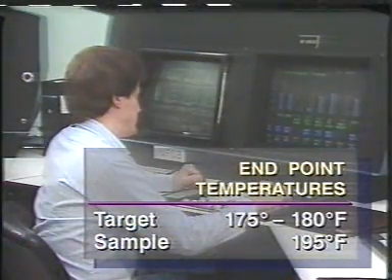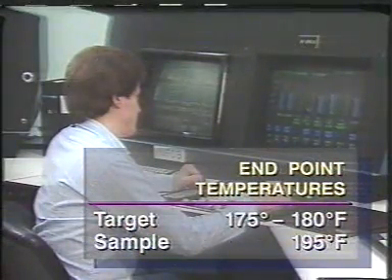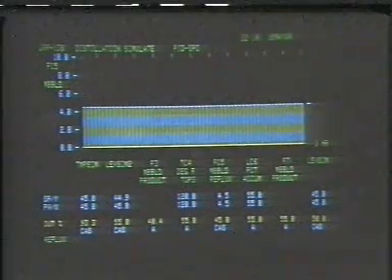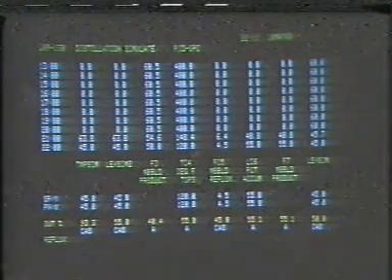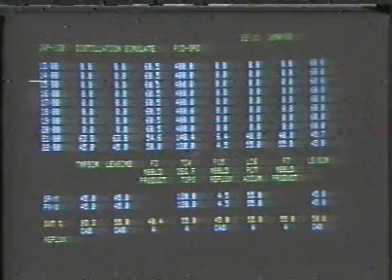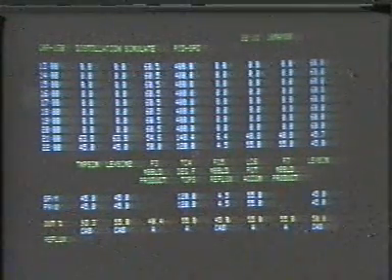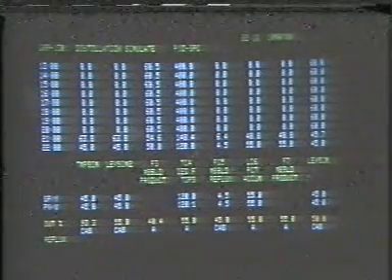In this situation, has the operator used logical thinking and made the correct adjustment? No. The operator in this example did not check all the data on the tower operating variables before increasing the reflux rate. This chart shows that the current tower operating conditions have not changed from the previous readings. Had the operator analyzed this data, he might have suspected that the endpoint test was inaccurate because none of the tower operating variables had changed. The most logical thing to do in this situation would be to retest the overhead product before increasing the reflux rate.